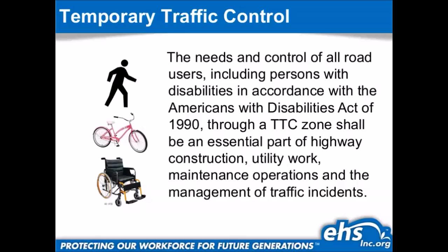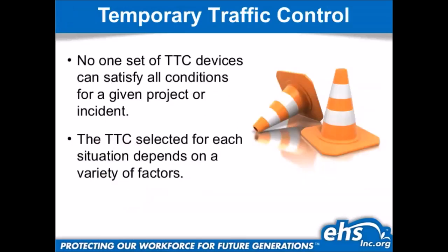The way it works is you have to give them safe passage through your site or no access to your site. If there's no way you can safely guide them through, you can't allow them to get to your work site. So again, the needs and control of all road users, including persons with disabilities in accordance with the ADA through a TTC zone, shall be an essential part of highway construction, utility work, maintenance operations, and management of traffic incidents.